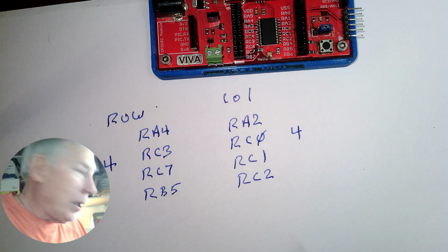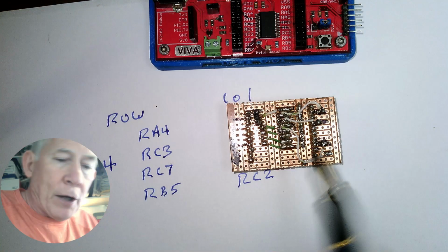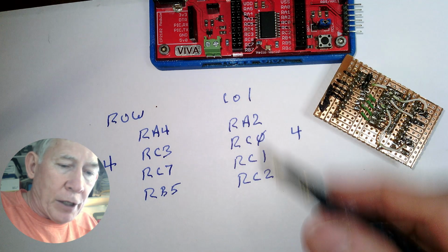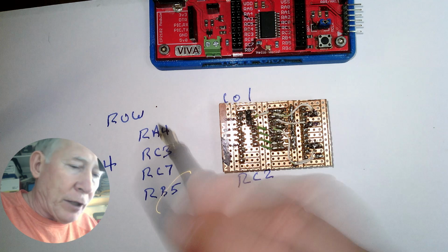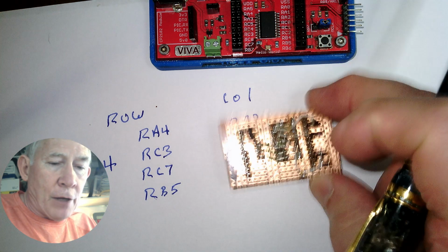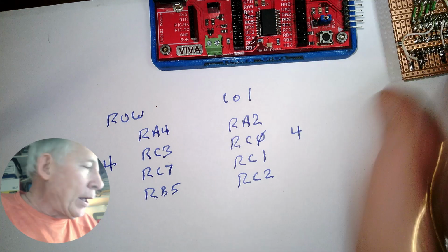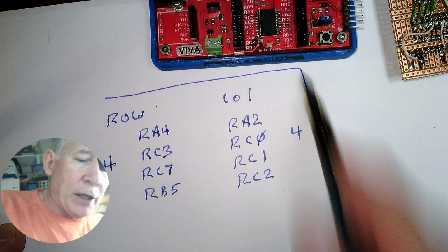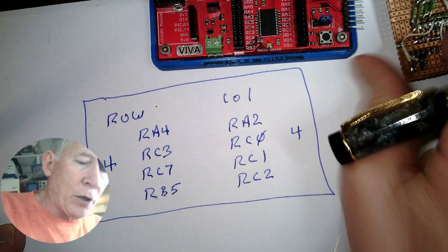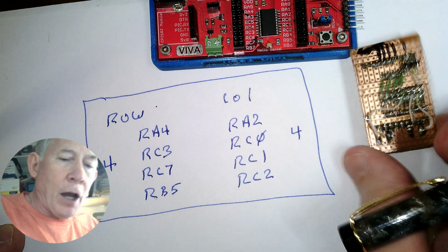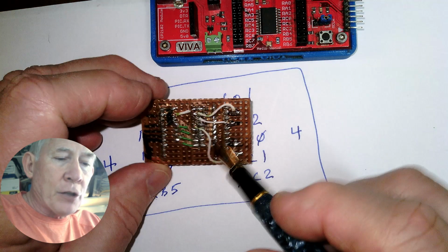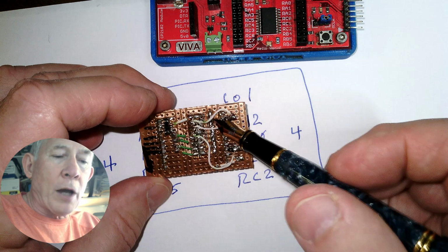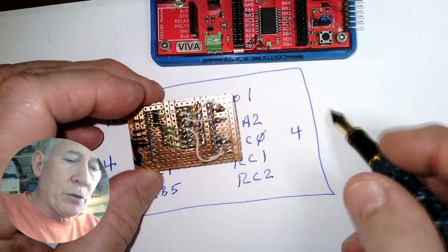And so that's why on my little interface board, the wires for the columns, the green ones, are all together because these are pretty close together, but the white ones are all over the place because they're spread out. And that's how that worked out. All right. And so that explains my choice of pins. So I had to do some thinking before I made this board so I could get everything hooked up correctly. And then I also had to put in these resistors and make sure my 8-pin header, all the wires coming out of my HEX pad, were pulled up to 5 volts through a 10K resistor.